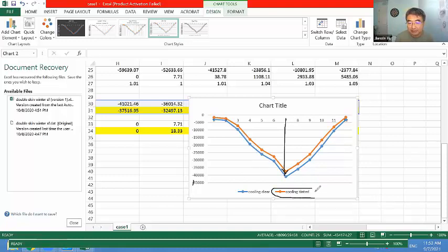But here, orange is the cooling tinted. So the tinted glass, of course, if you look at the absolute value, is smaller for the same month. For example, for May, the cooling load for tinted is only here, like 23,000. But for the clear glazing it's like 26 or 27-ish. So blue means that we have higher cooling loads. You have to spend more energy to remove more heat from the space. That means you're paying more for clear glazing. Okay, so that shows this.